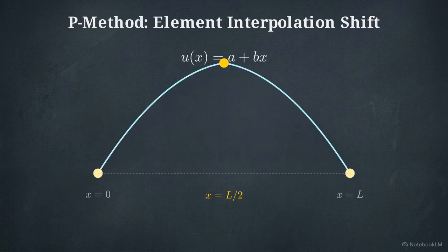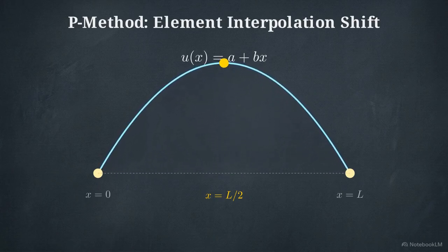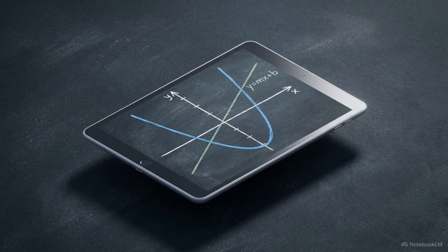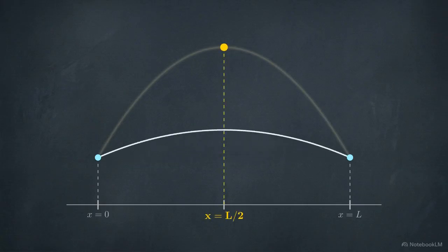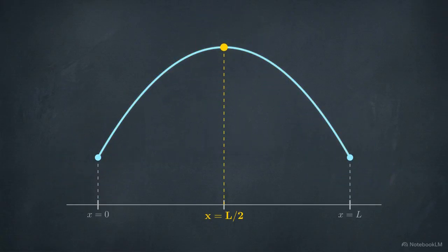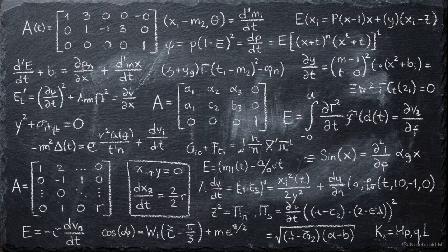With 3 points of reference, the predicted displacement field morphs from a rigid straight line into a continuous parabolic curve. Mathematically, we have transitioned from a first-order linear model to a second-order quadratic interpolation model. Shifting from 2 known values to 3 increases the element's internal accuracy, but it requires solving for a higher number of mathematical unknowns to define the element's behavior.